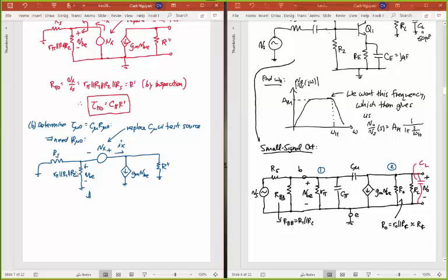And so I can analyze this circuit, but I think what I want to do is first convert this circuit into something a little simpler for me, at least to look at. And this is just showing you a trick that you can do in any circuit that you have. Anytime you have elements in series, you can juxtapose them. So this Vx is in series with the parallel combination of these two resistors here. Right? These are all going to ground there. So I can actually take Vx and stick it in the side that the resistors are at and draw my circuit like this.